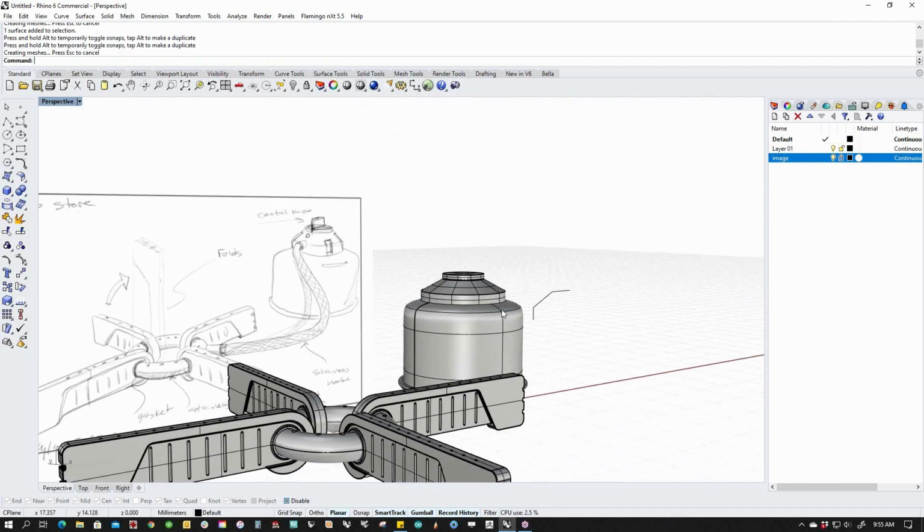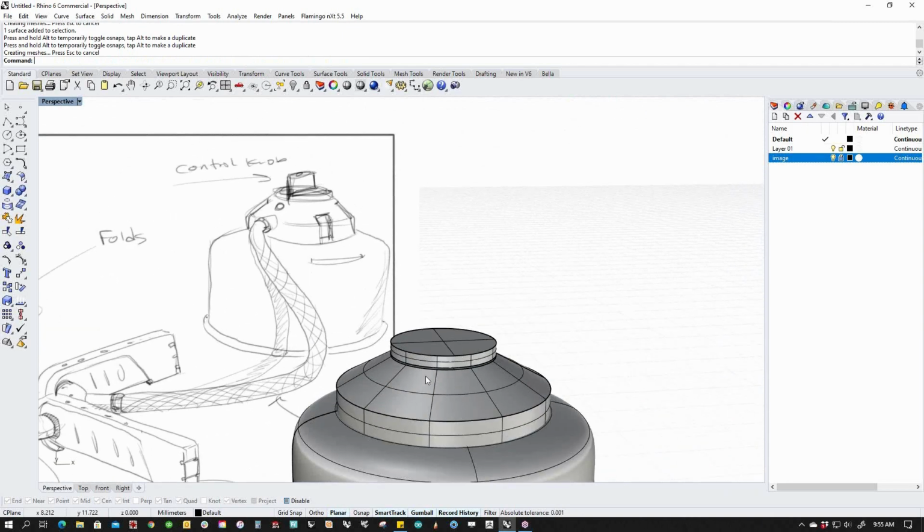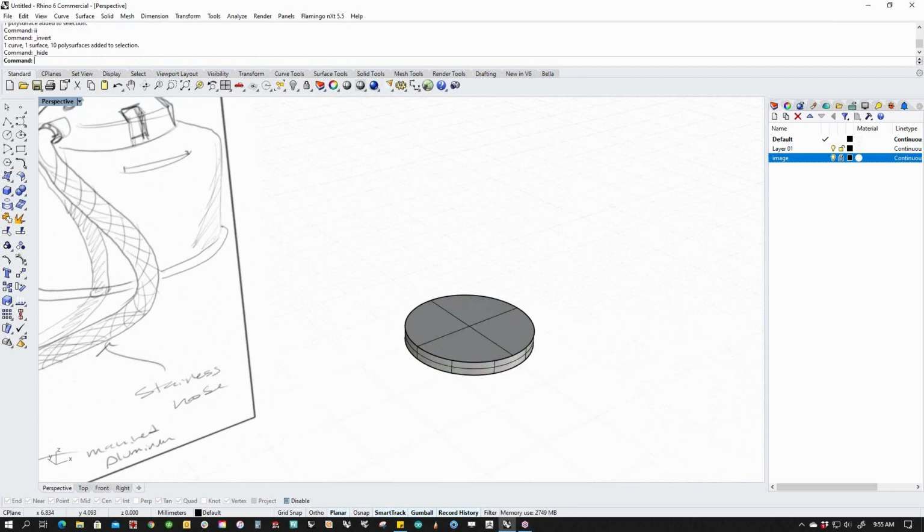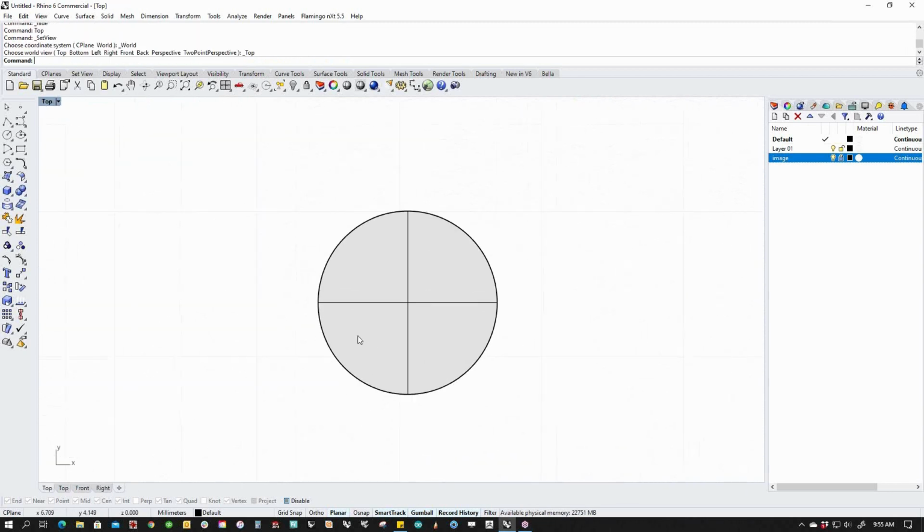This feels like it's complicated, but it's not. This is like so much gumballing, right? So much stuff that we just do that's easy. And then we'll do another cool trick, which is I'm going to draw a curve up here, center curve, rounded, and I'm going to snap it to the middle. I'm going to find the center. Because I don't have a center here, I'm going to draw a curve. I'm going to use a 3-point, go from here to here to here. Now I get a center.